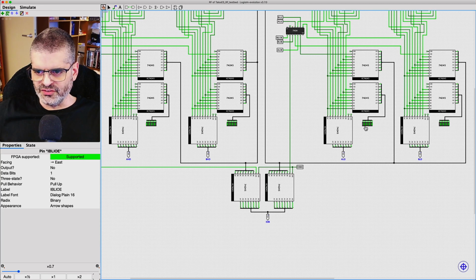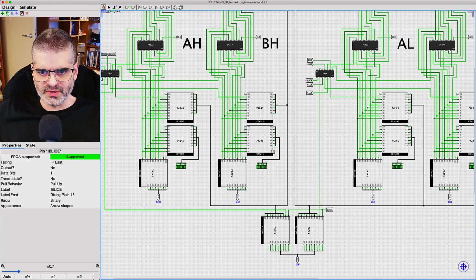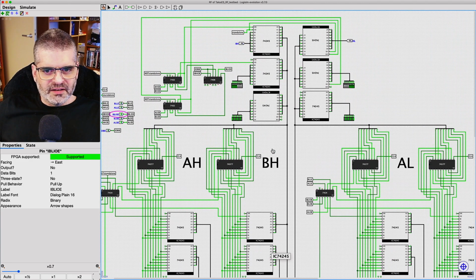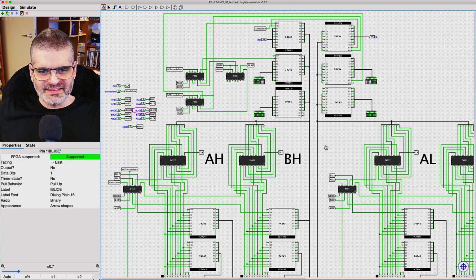This one is 0 1. So let's see, 0 1 0 1 0 1 0 1, exactly, and it's precisely the opposite of this one. So now we are driving the contents of A low via the local bus, via this buffer, towards the external data bus. So this is outputting to the data bus, inputting from the data bus we just saw with the blue lines. And this is it. That's a test of the entire functionality.